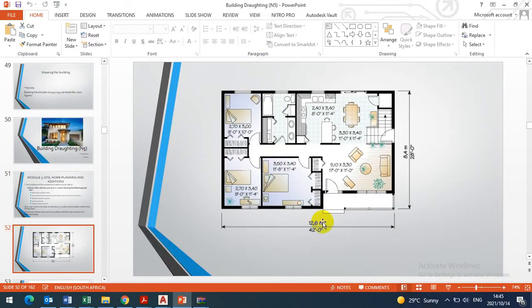This is an example of a finished floor plan. Although this floor plan is in inches, you can see it's 8.4 meters. When you're doing a floor plan in AutoCAD, you must type in millimeters, don't use meters. So when they say 12.6, it's going to be 12,600, and 8.4 is 8,400. Then these room area dimensions you see in here, 2.7 is 2,700 by 3,000. It's the inside length from corner to corner. That is the length times the breadth.